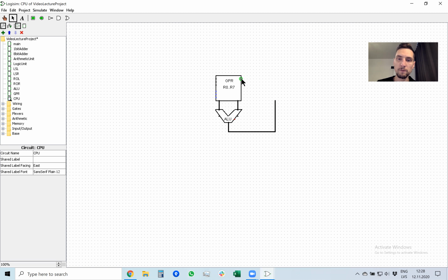So first, if we want to load a new number into register, we would need to take a number from flash memory that is pre-compiled, which says what number we want to get into some register, and forward it to general purpose register block. Secondly, we maybe want to take a number from random access memory. Thirdly, maybe we want to read number from arithmetic logic unit result. And finally, we would also want to read the status register, which is produced by arithmetic logic unit.